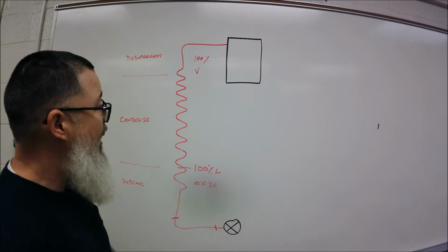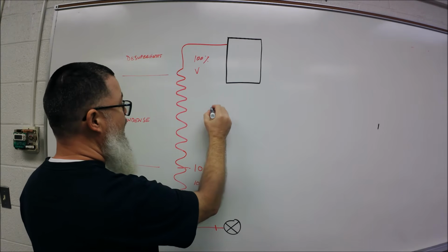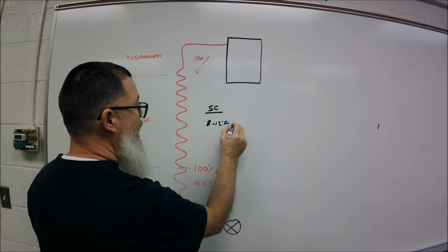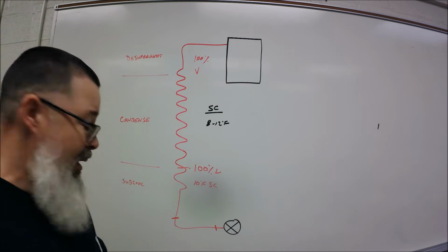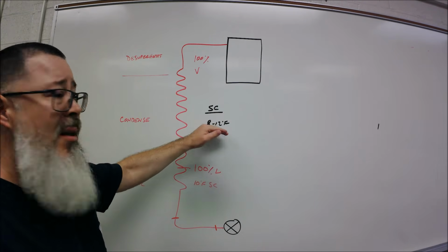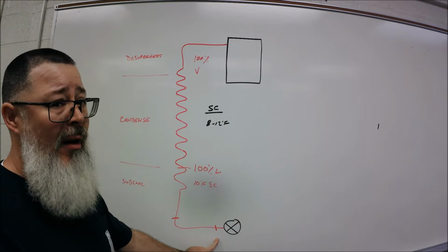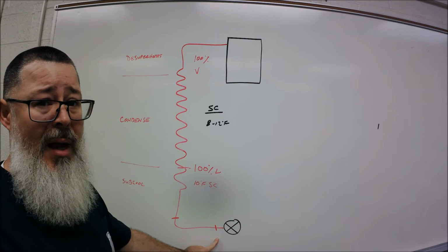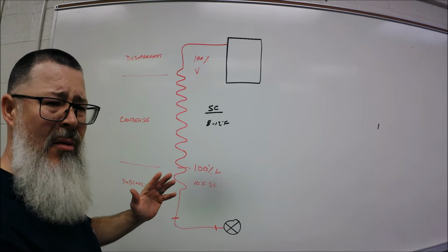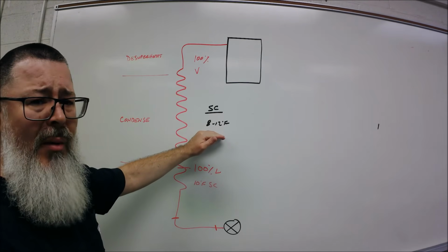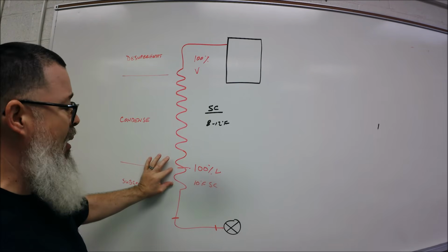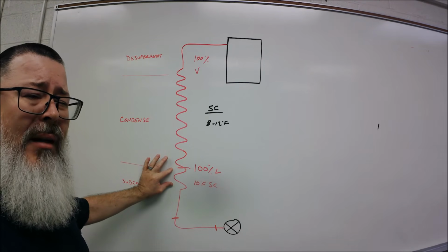Something I didn't put up there, but the books will tell you that subcooling is probably going to be 8 to 12 degrees, maybe 10 to 15 degrees. You can look at manufacturer specs and stuff like that, but what does that mean? So 1 degree, very close. We barely made liquid in time. 5 degrees of subcooling, well, we made a little more liquid. Still not great. If we go with the recommendation, 10's a good number. But what does 10 degrees look like? Oh, it happened kind of in the coil, right at the end.